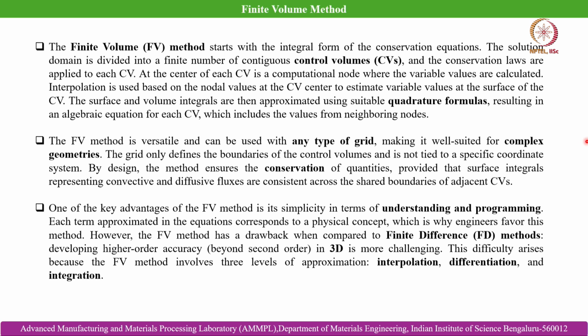So, finite volume can be implemented to any kind of grid, but again it is easier in case of structured grid. However, because of its simplification and ability to adapt to any kind of flow geometry, it is often very popular with fluid flow problems, where the fluid domain is often changing, somewhere the flow has a thicker cross section, somewhere there is a thinner cross section, which is not otherwise the case in solid mechanics problems.